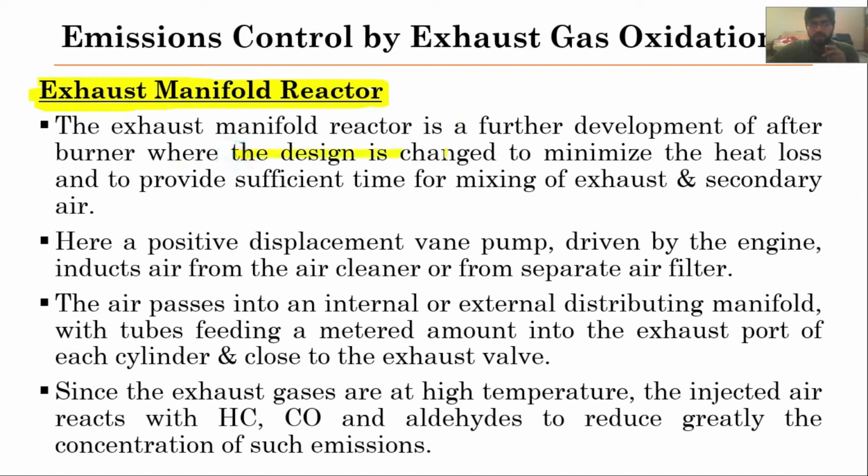The design is changed to minimize the heat losses, and also to ensure proper mixing between the exhaust gases and the additional secondary air which is injected into this exhaust. It provides sufficient time for the mixing. So not only is it reducing the heat losses, but it is also providing sufficient time for the mixing of these exhaust gases and the secondary air.